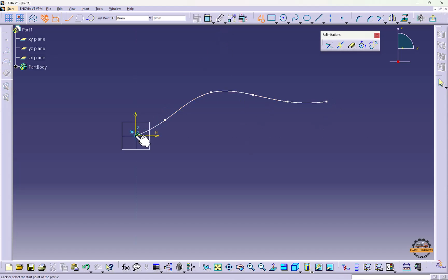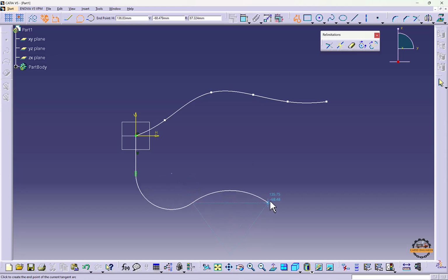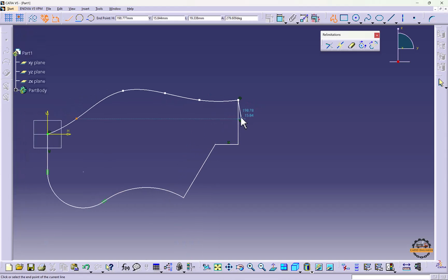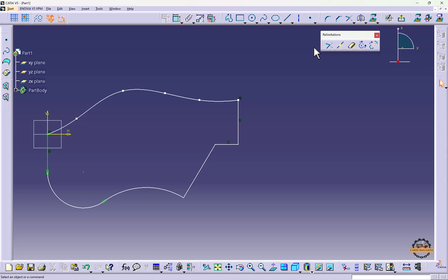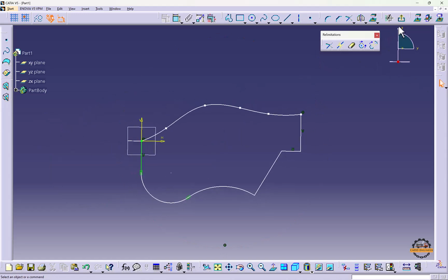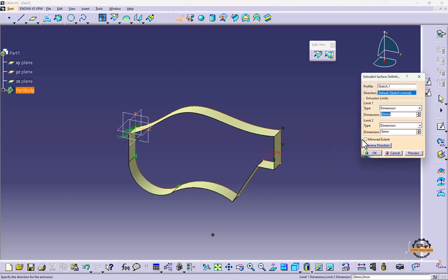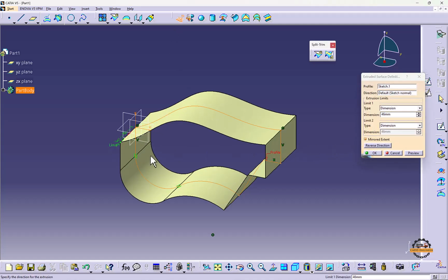I'm making this a closed surface kind of thing. Like this I just created a sketch and I'm going to close it with the surface. First I'm going to extrude it with the surface. We'll go to Extrude, add some surfacing, define the depth and do OK.